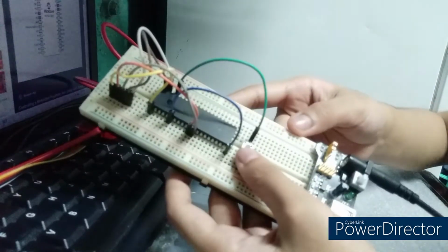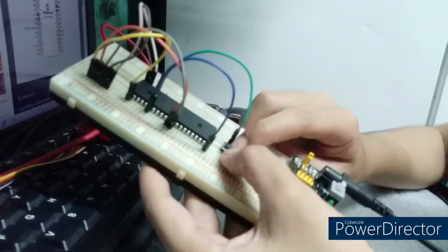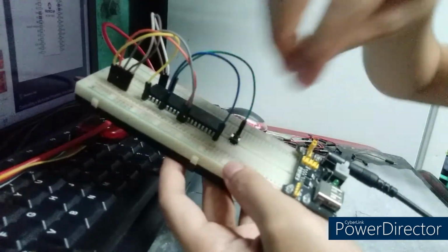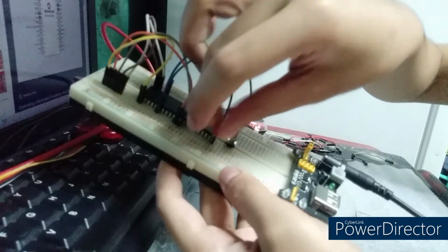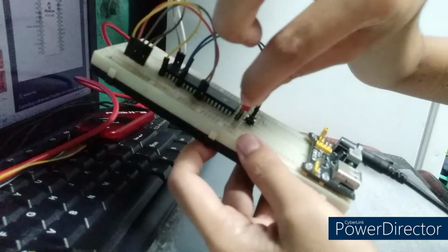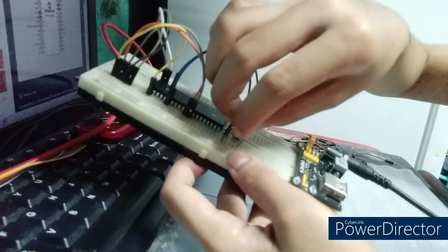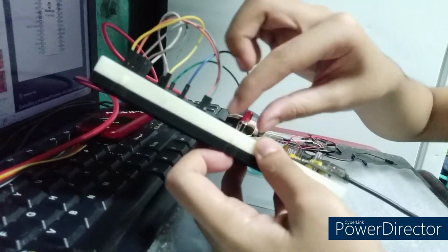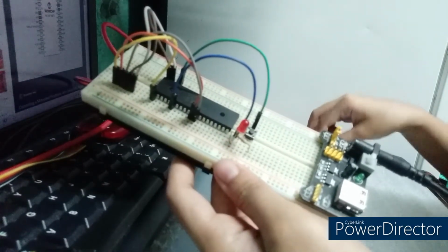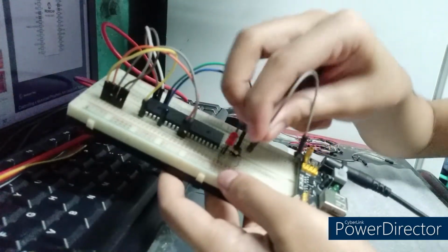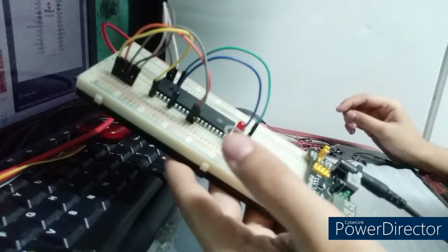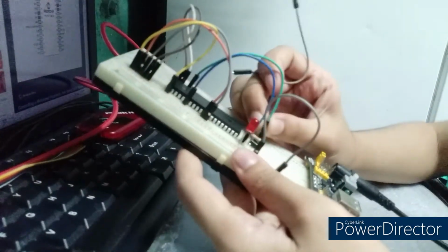Let's put our tactile switch on the center of our breadboard. And then let's put a resistor and an LED first on pin number 6 of our IC, and do not forget the 360 ohm resistor here so that our LED will not be shocked by the voltage. And then do not forget the proper grounding of our circuit. We will ground our LED here. So let's put a negative polarity here, and then let's ground our tactile switch as well.